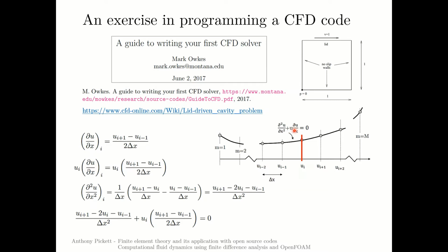In a finite difference scheme, we would split up into a number of points in this direction. Let's say we're interested in finding out what's happening at this particular point. This du/dx, or this gradient, is equal to this value minus this value divided by this distance, and this is exactly what's given here. So we can get an estimate of this gradient from these actual values.